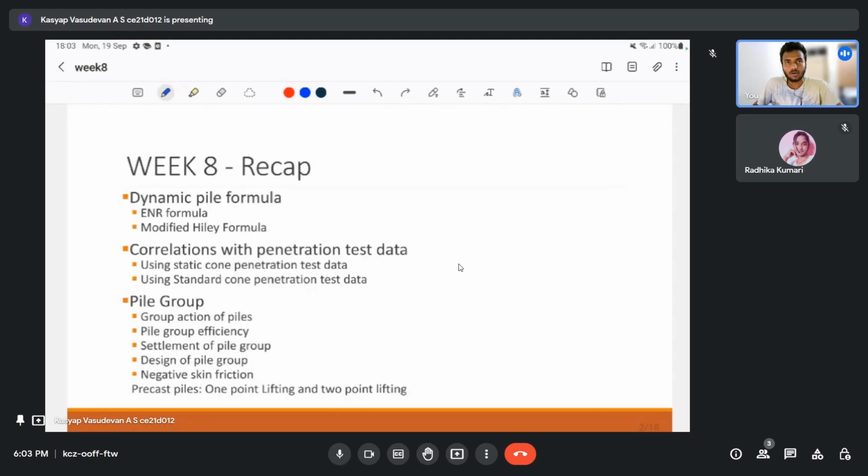So we can estimate roughly the energy applied on the pile, and we also know the work done, that is the displacement of the pile after the hammering is done. By judging these two quantities, the energy applied as well as the work done, we can roughly estimate the capacity of the pile.